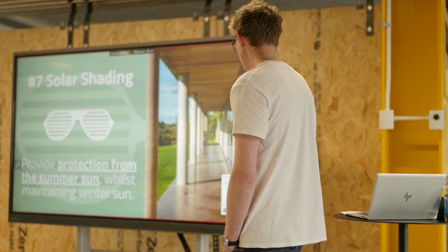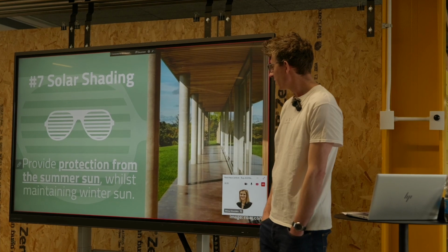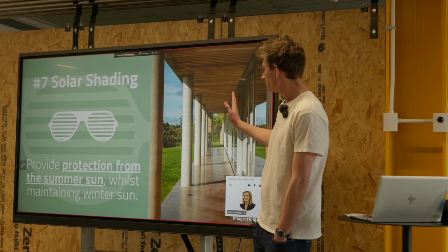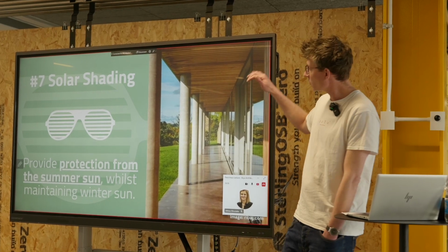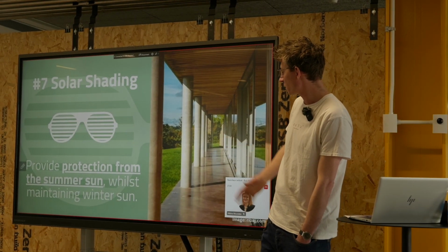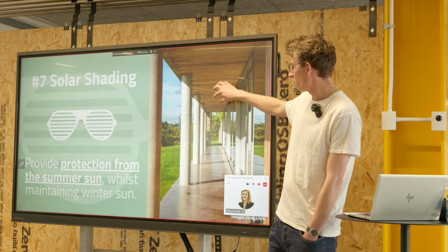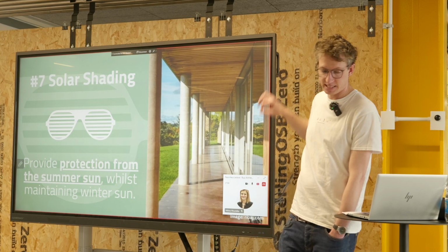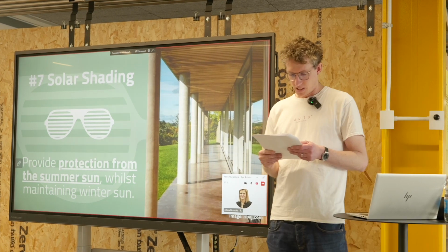What is also worth bearing in mind, and I'll come on to this again in a few minutes, is any kind of projection or canopy which fixes onto the facade, you need to be considering as a potential risk as well for cold bridging. So these elements will obviously get cold. How is that cold being prevented from coming inside? And it's trying to think about those thermal breaks as well for the solar shading.